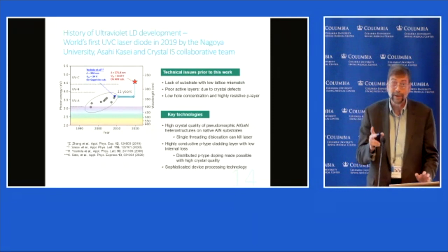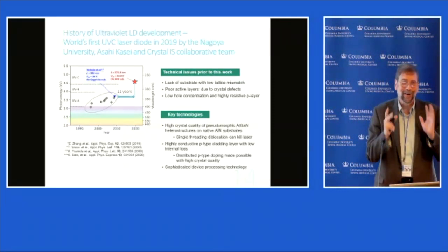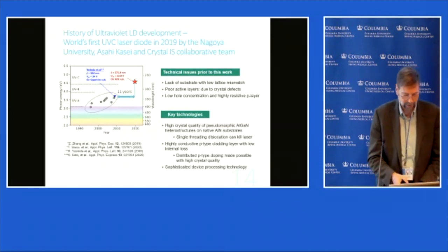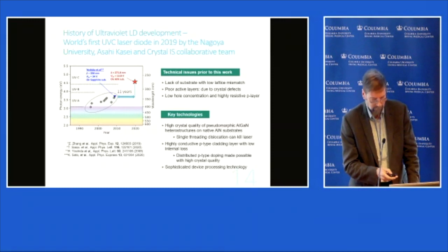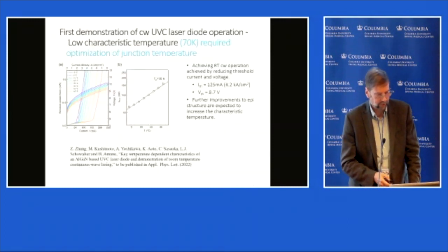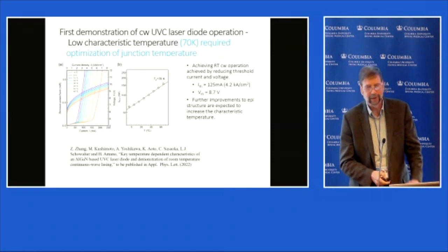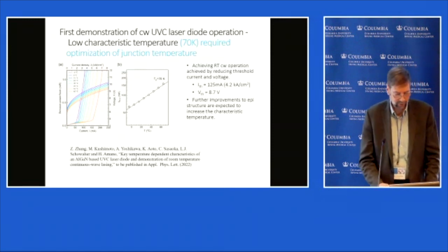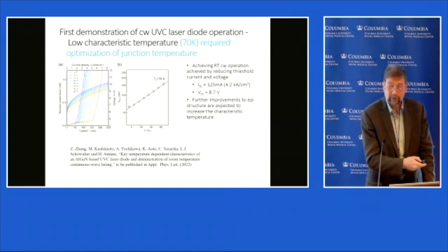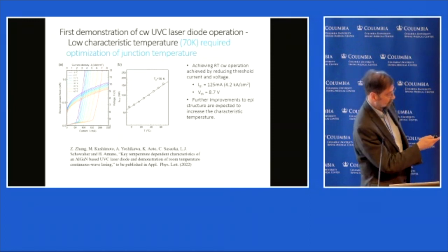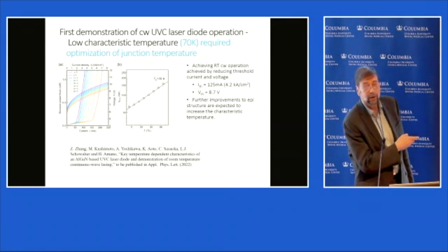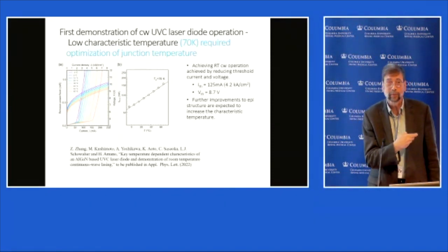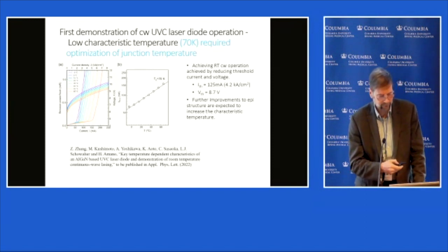And what I want you to believe, because it's true, is that this also applies to making the Far-UVC LEDs, that this same kind of technology will enable that to move much faster now. Just some of the characteristics: initially the laser had to be run pulsed because of the temperature effects. Now they're able to run CW. There is a strong temperature dependence on that, and that's also an indication of defects that we want to improve. So that's typical of a material that still has room for improvement, to have that strong temperature dependence.